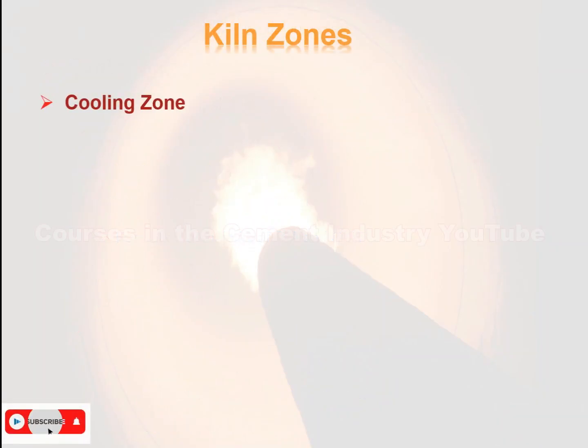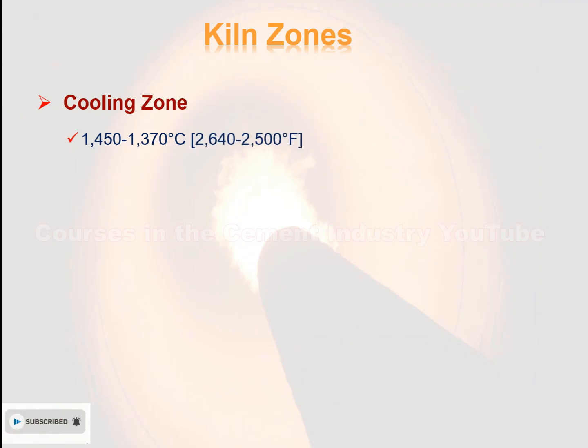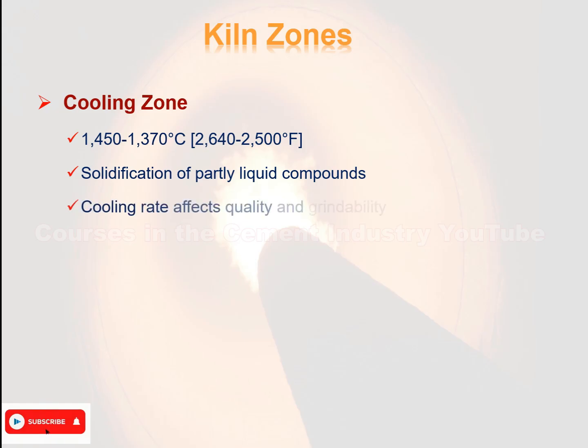Cooling zone. 1450 to 1370 degrees: solidification of partly liquid compounds. Cooling rate affects quality and grindability. Alite crystal growth. Freezing of MgO.